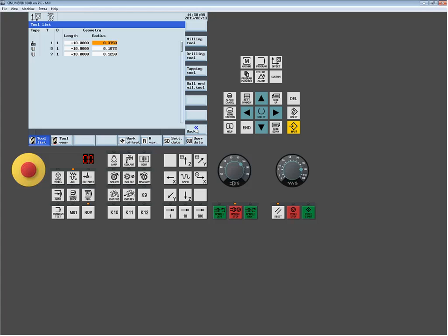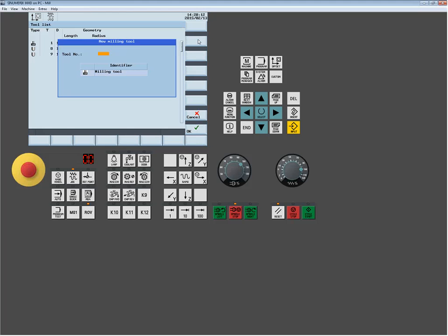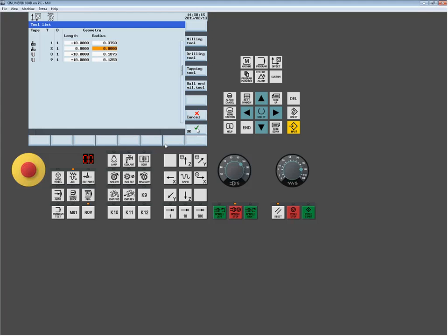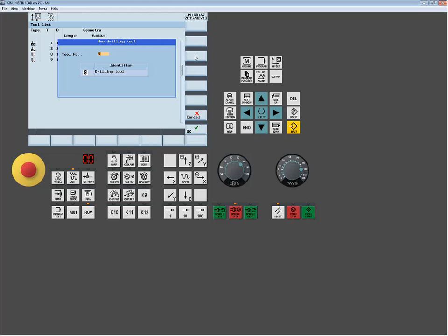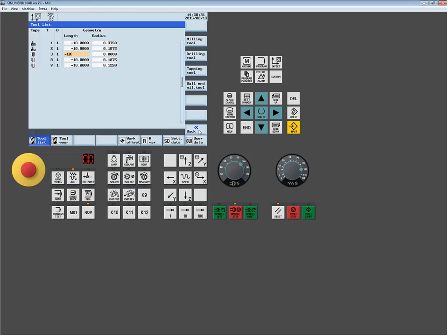Well, what's really happening is if I was to really run this part, it's actually loading the offsets for tool 2 because they have set this machine up to prefetch, but this actual machine isn't designed for prefetching. So watch what happens when I simply just delete this instruction that's not needed. Now, if we go to simulation and we rerun this part, now we see a completely different cutter path.